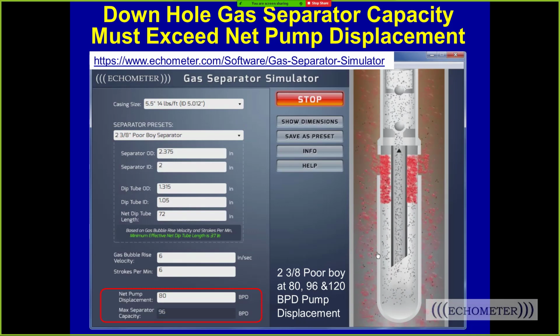If you have a problem with foam, then when you open your tank lid at your separator tank, you'll see a bunch of bubbles foam out of your tank, because that's where the gas velocity is low. So a gassy fluid column is liquid with gas flowing through it. It's not foam. So that's the answer to the question, I think. Great answer, Lynn. Yes, I think that clarifies a lot.